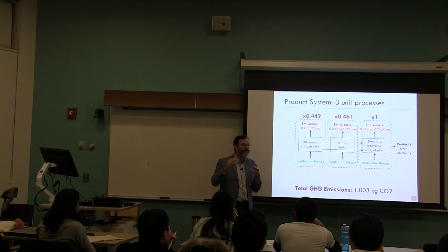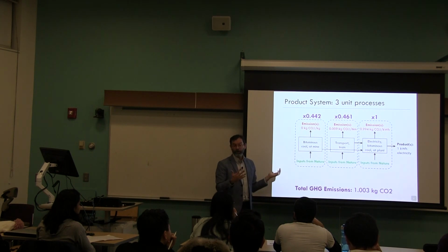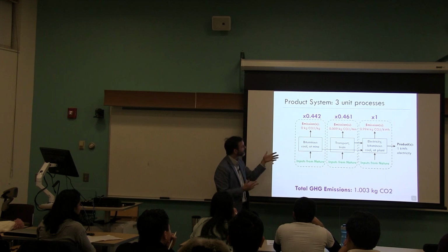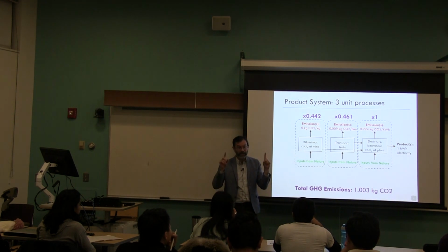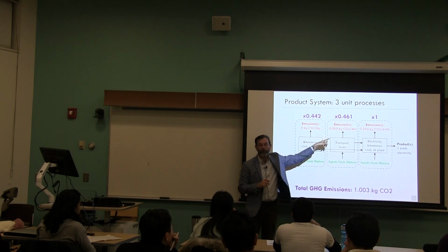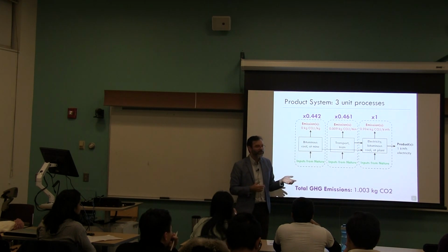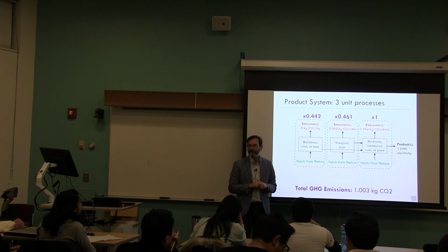Put those numbers together and figure out how much CO2 is being emitted per ton kilometer of the train moving. So the heavier a train is, the more fuel it needs to move a certain distance. It could be a direct measurement, or you could say, I know the train is consuming a certain amount of diesel, and then do a mass balance on the carbon in that diesel, because it has to go somewhere. It goes up the exhaust pipe as CO2. There's no other place for it to go, assuming complete combustion. Either of those methods you can use to get what's called an emission factor, emissions per unit of whatever is being delivered by that process, in this case, the ton kilometer.